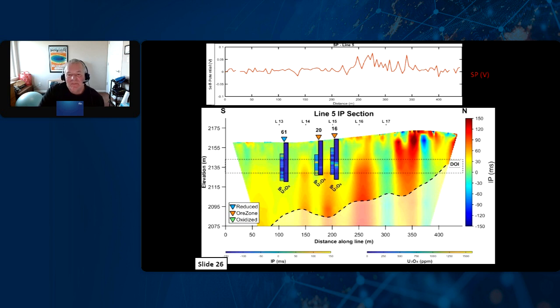So this is that same line. We're in the reduced area out here. We have no real IP response, a little bit at depth. But as we enter the zone where IP is expected from the drilling results, we start running into anomalies at the depth we would expect within the sand. So this hashed square is essentially the sand layer depths that we care about.